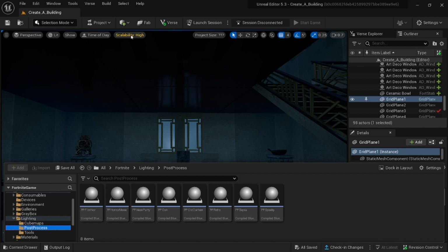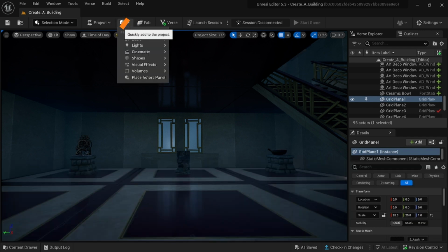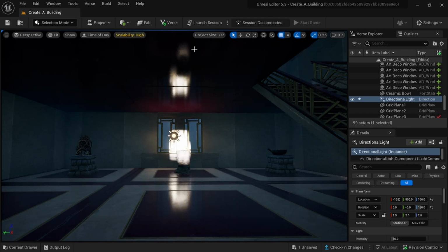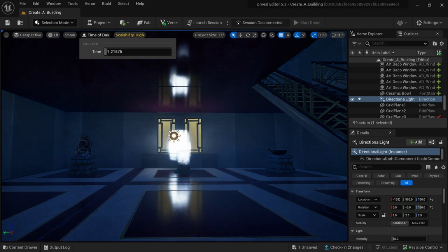Directional lighting is lighting that originates as a sun-like light source. It can illuminate large areas from a specific distance and direction. To use it, navigate to the Quick Add button on the toolbar near the top left of your screen and click it. A drop-down will appear from which you can select various types of lighting. Here you can select a directional light. You can also use the time of day setting to see what effect the hour of the day has on the lighting. In general, directional lighting should be set high up in the sky since it usually simulates the sun.